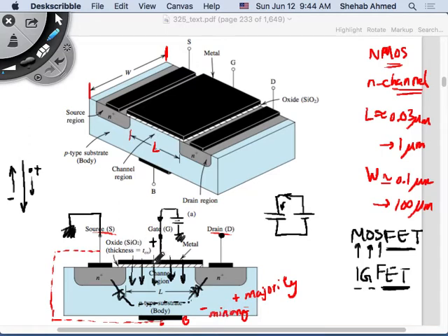I mean, they cannot penetrate the gate. They will go up. So I had a depletion layer that is now free of the majority carriers, and then I attracted all the minority carriers up. So I created a region here that is full of all the minority carriers, which are electrons, and I've pushed down all the majority carriers. So I've created what is called a channel, in what is called the channel region. I've created this channel now underneath the insulating material.